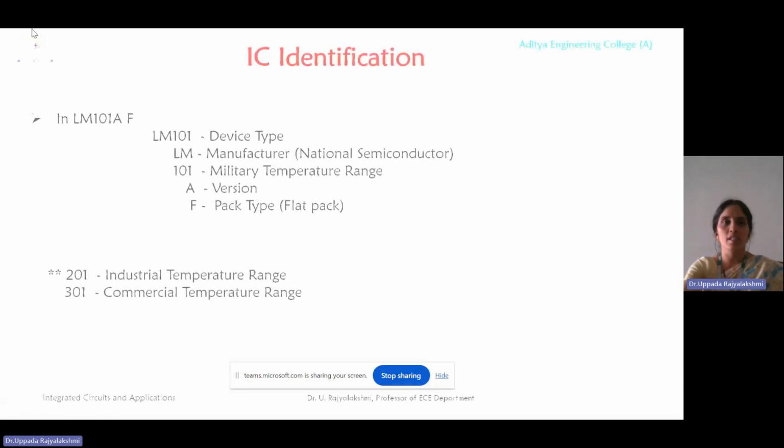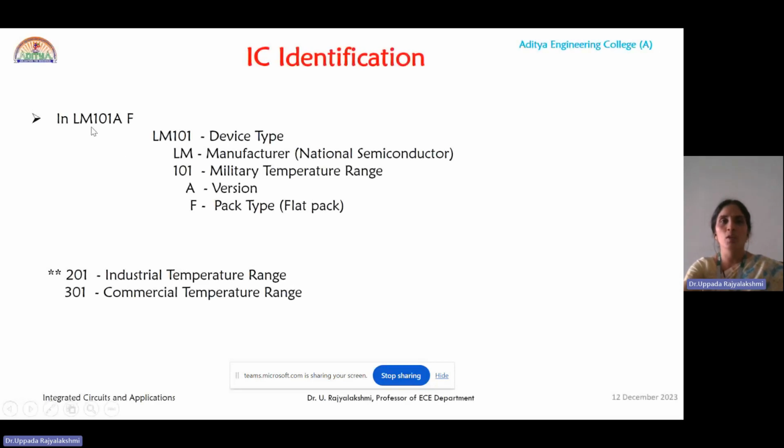You can see one more example, LM101AF. Here LM101 represents the device type, and LM is the initial provided by National Semiconductor. Here 101 represents the military temperature range.